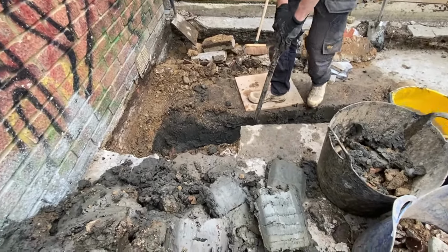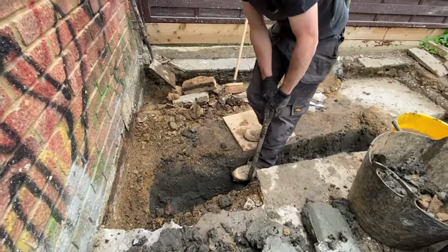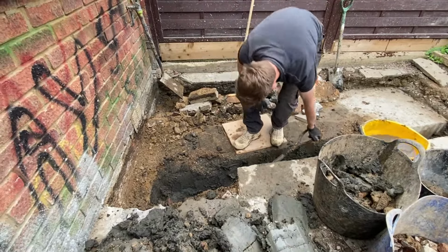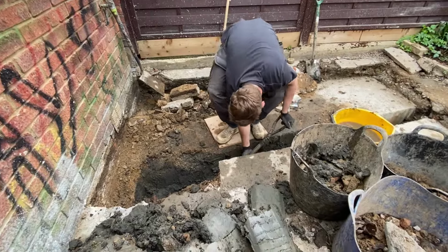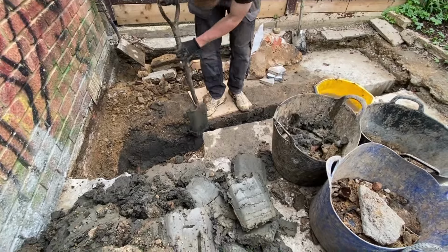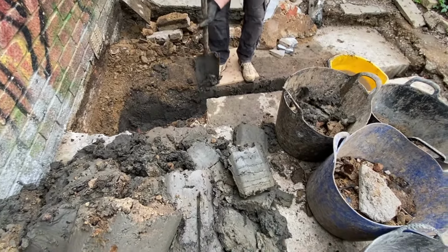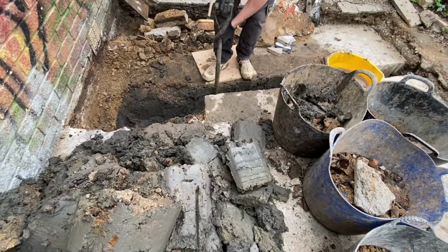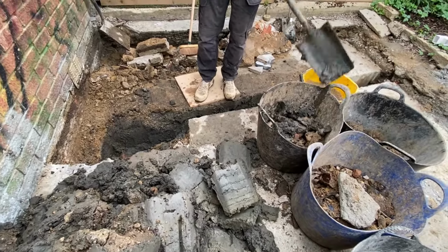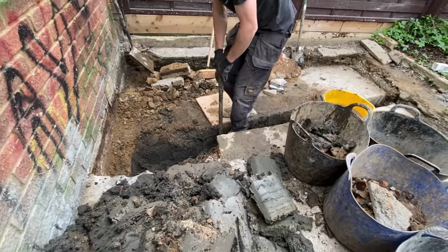So obviously when we're putting the rodding pipe in, the access pipe, it has to be at the same level as the sewer pipe. So that's obviously quite a lot lower than the floor level that we're looking at for the extension. So we're having to dig down so that the pipe can run flush and we're able to get that access in. So this is the old patio. This was previously the patio of the house. This is where the 3-metre extension is going, so you can see the foundations are running around the edge of this, and we're now just having to dig out the access to put in that rodding pipe.